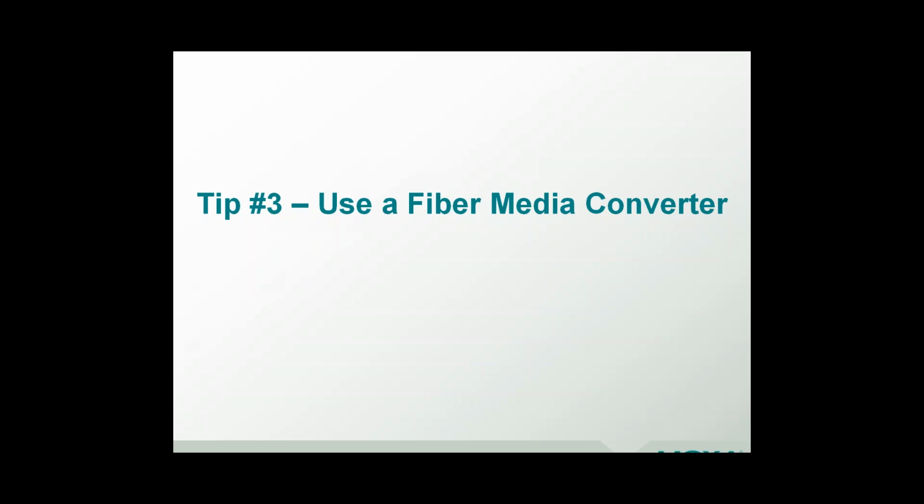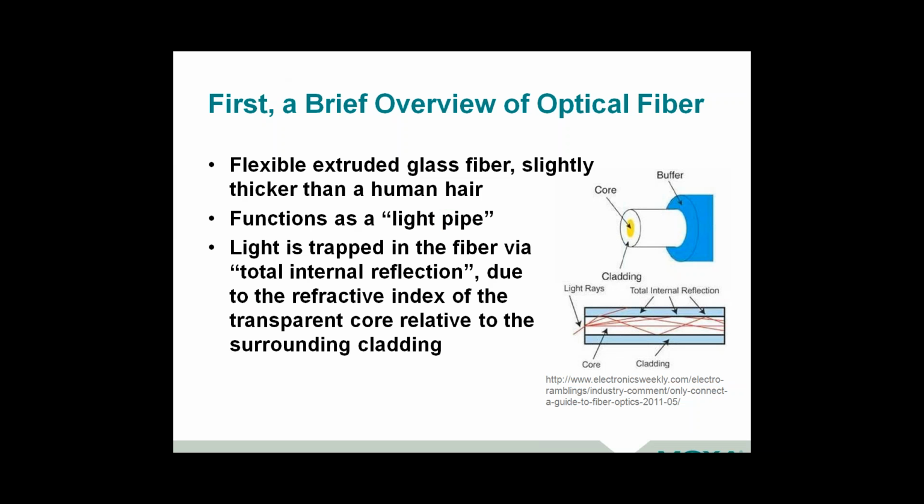So great. Well, I guess fundamentally, you folks know that there's another technology out here called media converters, which can allow us to extend those connections. Let's take a closer look at some of the technology driving that. For those of you who aren't familiar with it, the simple concept is taking those electrical signals on copper cable and converting them into short bursts of light carried over a piece of typically glass, but in some very specialized applications, it can be plastic fiber optic cable.